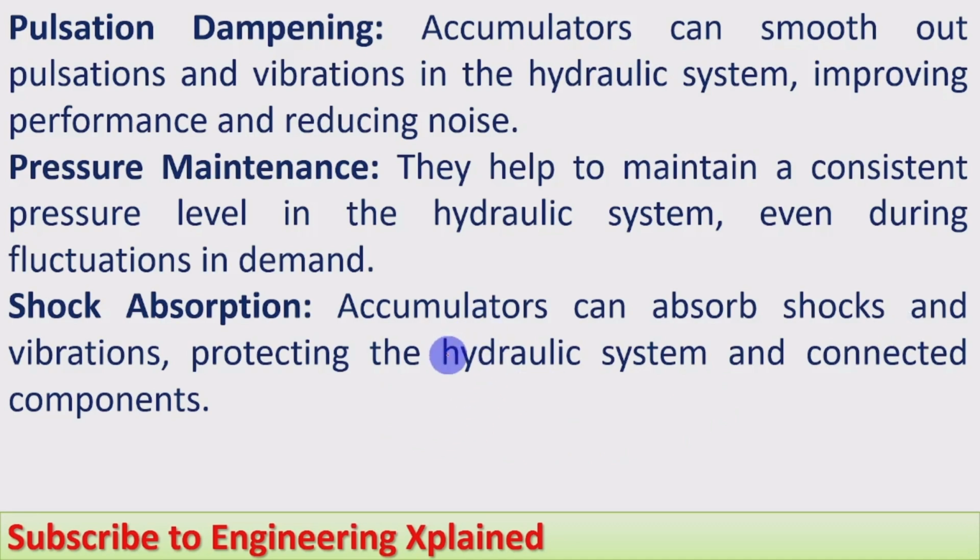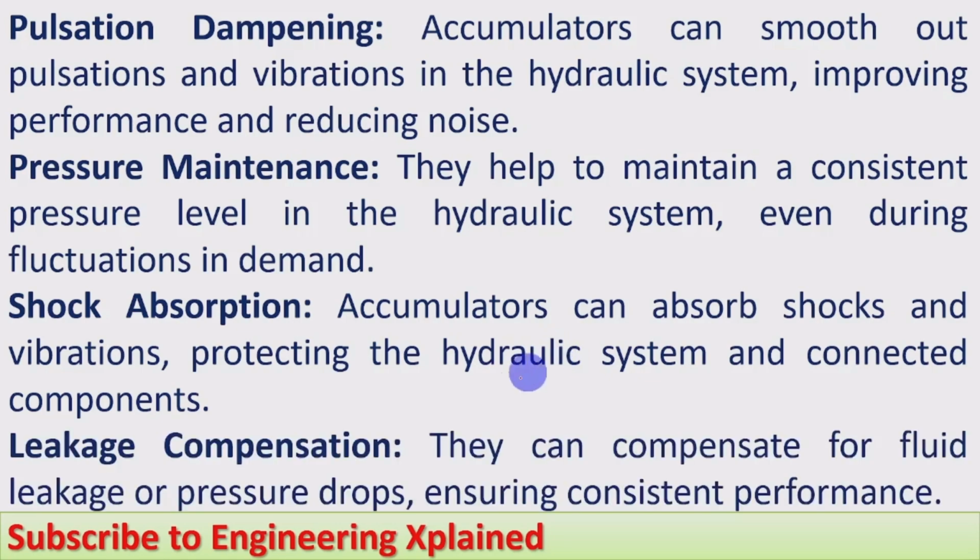Here the shocks are produced during operation. Those are due to the variation in the flow and the operation of the various hydraulic components like pumps and actuators. There the shocks will be produced, and those shocks will be absorbed by using these accumulators.